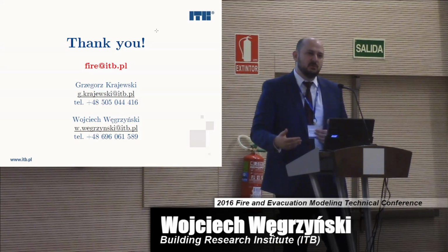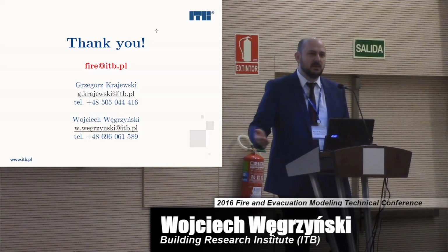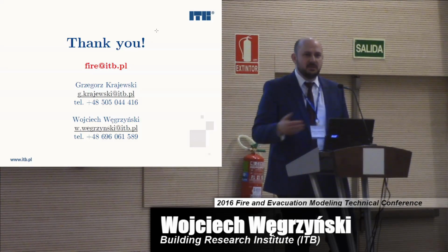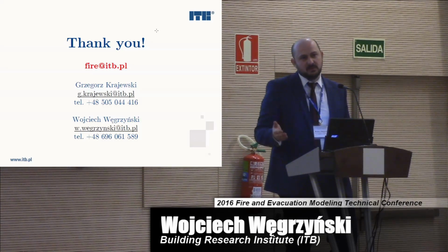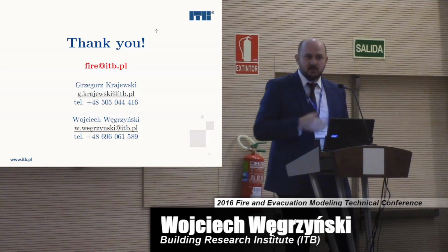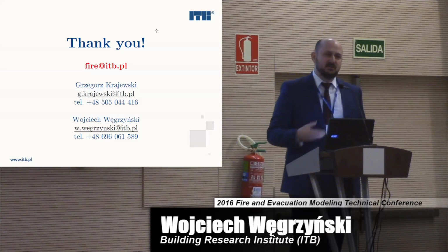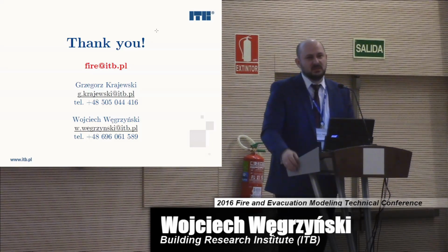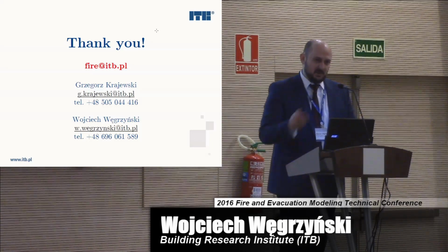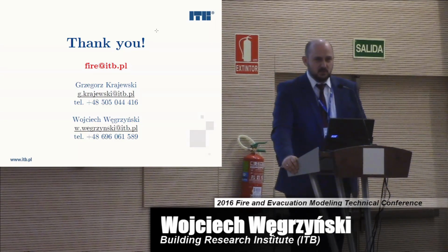But you could do as well as we did: just build a model without the interior, run some transient simulations for like a minute or something to resolve the flow inside the room, and then have a general good idea what's happening in the room and in the domain, and then just pick, okay, this is the worst case scenario, and work further on it, building the domain to include the interior fire and just do normal CFD as you would do for a fire with this additional boundary condition being wind. That's what we would do.